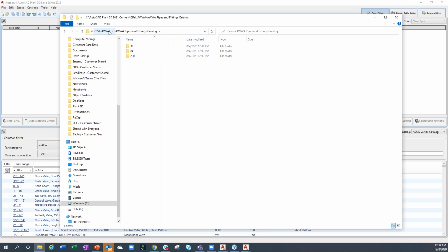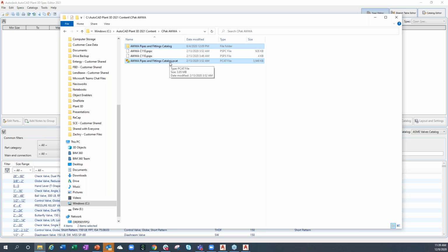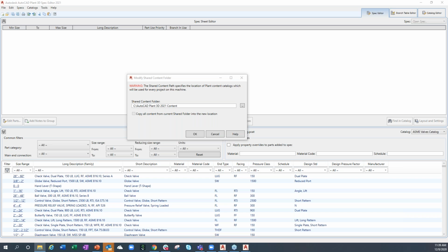See, now for me, I could zip up this catalog and this folder, knowing that's all I need for that catalog, because inside of this folder is going to be all the DWGs and the source DWG file that had all the blocks in it. And then I don't have to worry about managing my catalogs in all these different places. So hopefully that was a good enough shotgun explanation there.